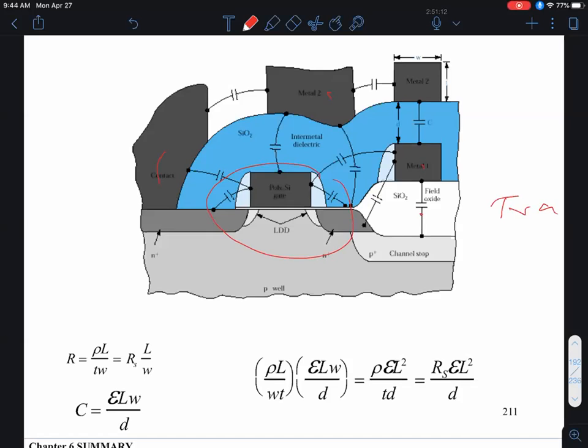Now, what you find is in a typical chip today, if you were to show the cross-section, you don't have a single layer of metal interconnects. You have multiple layers of interconnects, okay? In fact, in a modern computer chip, you may have, maybe 20 layers of metal interconnects crisscrossing each other, okay? And the reason you want so many layers of metal interconnects is the same reason why you have overpasses in a city like Austin, right? Because imagine what the traffic flow would be if you didn't allow any overpasses, right? You'd have huge traffic jams.